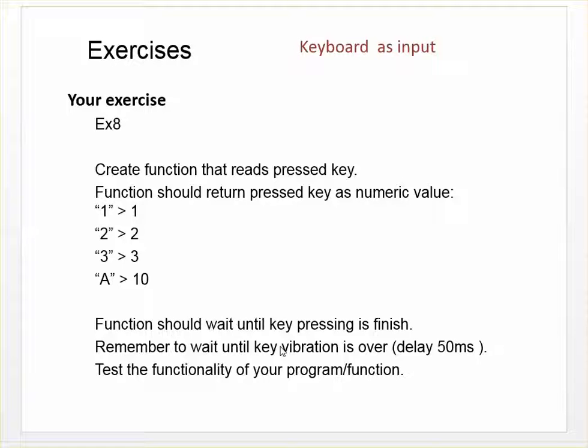You could notice that your program seems to be crazy if it's not working in a feasible way, if you are not trying to prevent the key vibration. Usually you can do that by putting only a short delay into your detection when you detect the keys, so the delay will usually handle the case. And of course then test the functionality of your program to see that it really works, but you can use that 7 segment to output the numbers.